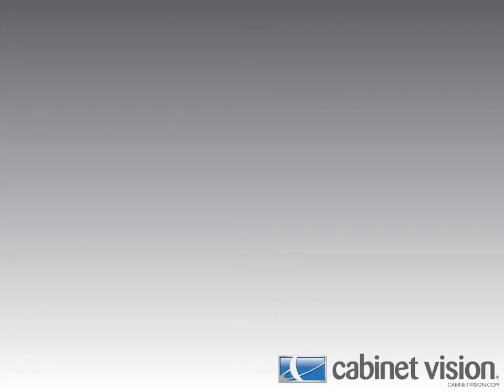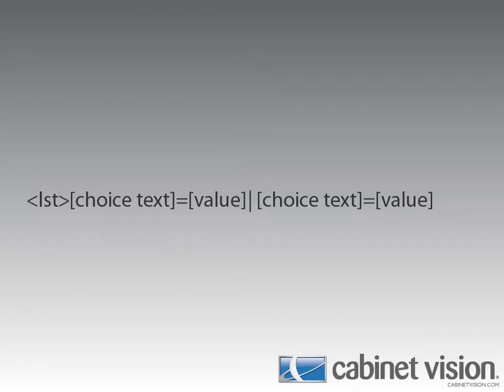We do that by typing in the LST keyword in a set of angled brackets. Next, we start to define the options of the list. That format is the choice text, the equal sign, and the value that the option is supposed to equal. If we want additional options, we need to add the pipe symbol, and then we can add another option. We can continue to do this for each option we want. This is how my choice list for my style width parameter looked, properly formatted.